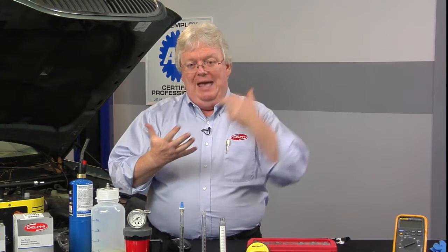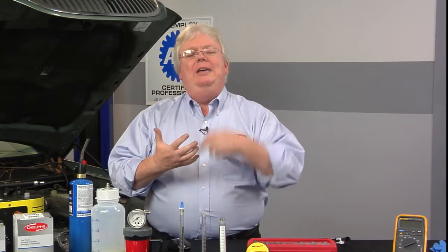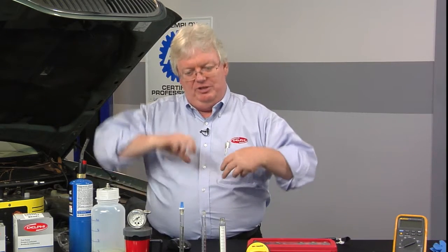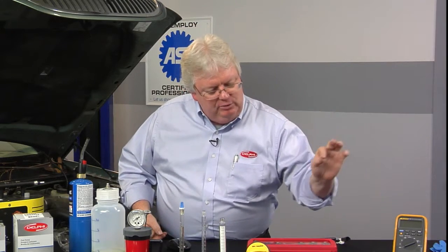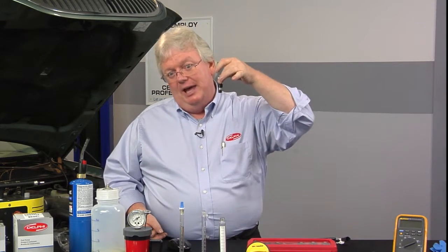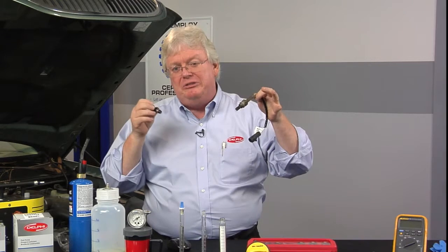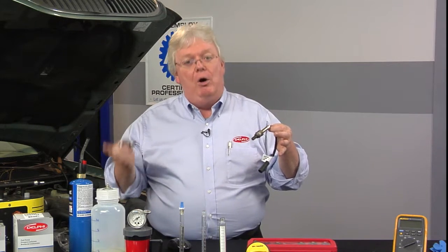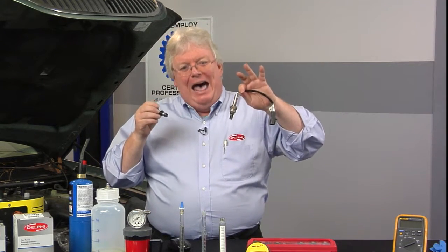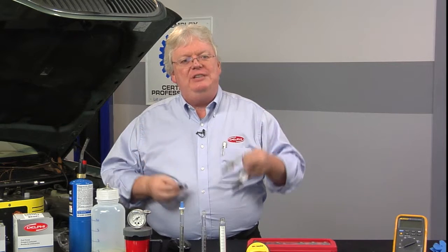What is the mass airflow, the MAP, the coolant, intake air, all those analog and digital sensors the computer looks at, and then you start cranking RPMs and so forth, and it makes the decision to spray the fuel injector X amount of milliseconds. And after the fact, if that's too much or too little due to engine problems or mechanical variations, variations in fuel, for example, we'll do a little live demonstration on alcohol in fuel, as that is not perfect, then the O2 sensor sees that, and we make adjustments.